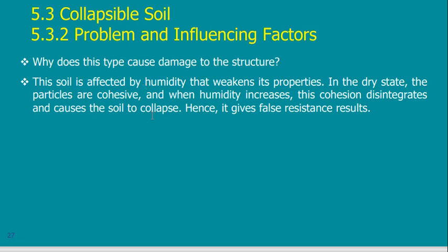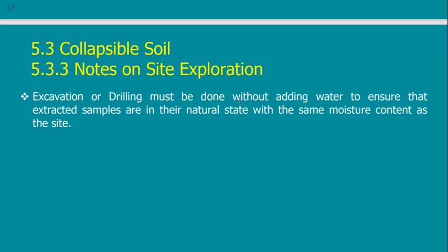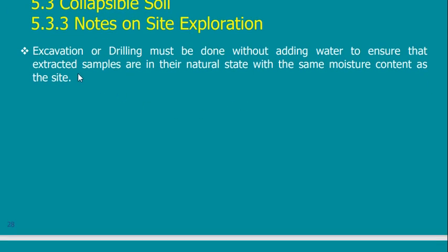We discussed this and we said that it is not humidity, it is wetting. When water comes and fills the area, it causes problems again. We said that in site investigation we have to follow a good procedure, because if we use water in drilling, then we are going to change the characteristics of the soil.